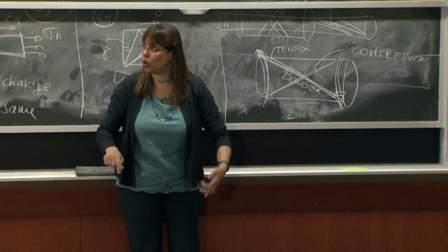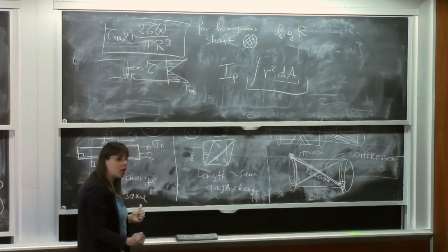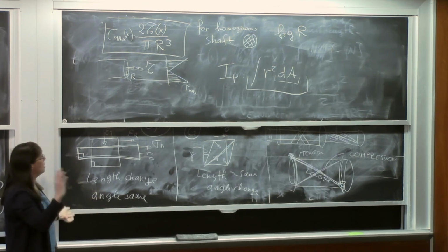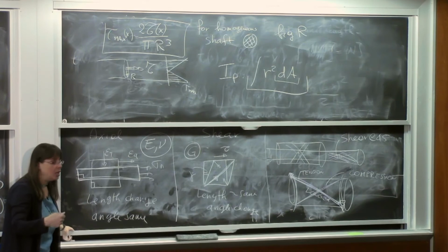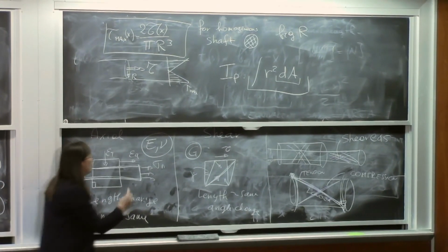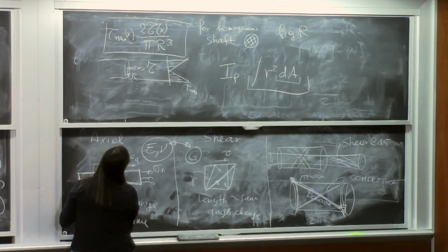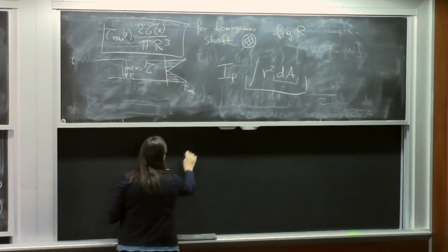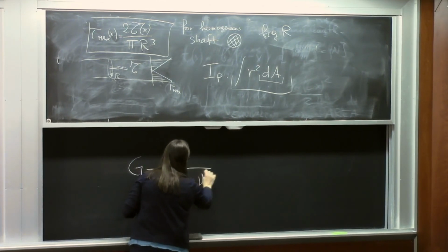Okay? So these two worlds talk to each other. And we're going to do the talking at the very end of this class. Like the last lecture, when you think you're free, we're going to go back to stress and strain and understand how shear and axial loading are related. And because shear and axial loading are related, I leave you today with an amazing fact, that G is equal to E divided by 2(1 plus nu).